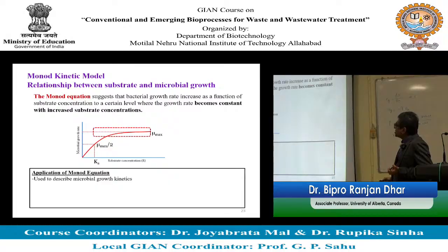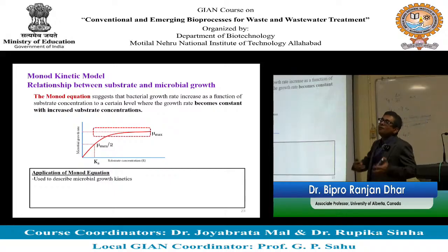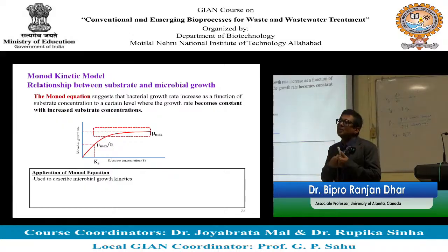As for application, the Monod equation is used to describe microbial growth kinetics, and it works for most biological wastewater treatment systems. In most biological treatment systems, the fundamental step starts with the Monod equation.